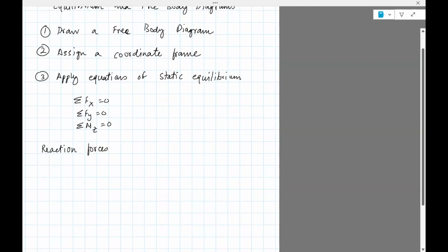Okay, so when we talk about beams, these beams have to be supported in some way or the other. There are different ways in which beams can be supported. One is a roller support. Here, there's a beam, and I'm just going to show a section of the beam. We're not interested in what's happening on the right side, so there's a cut. Here is a roller. This is the ground. So there's a ground, there's a roller on that, and on top of it there's a beam.